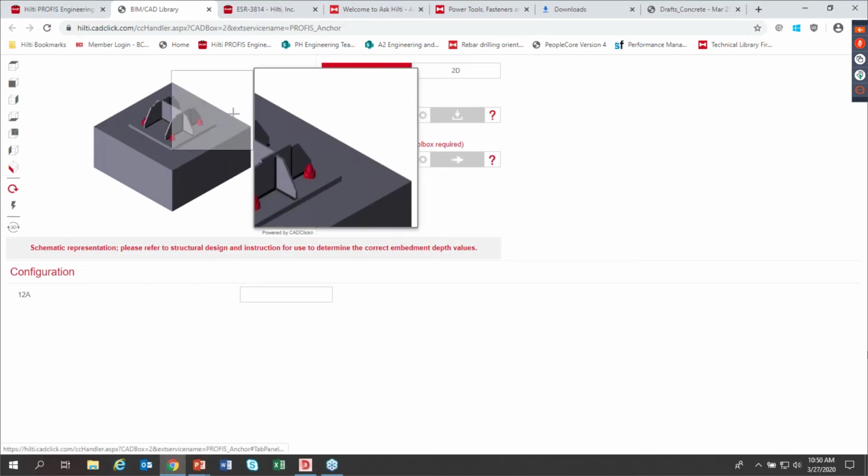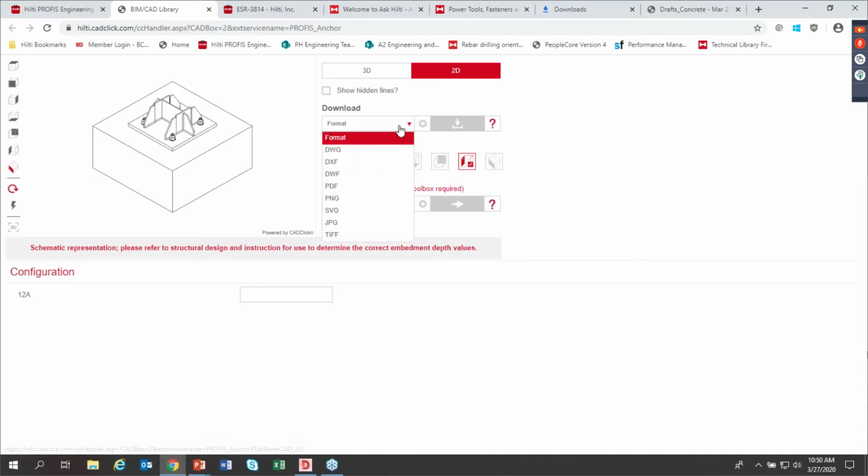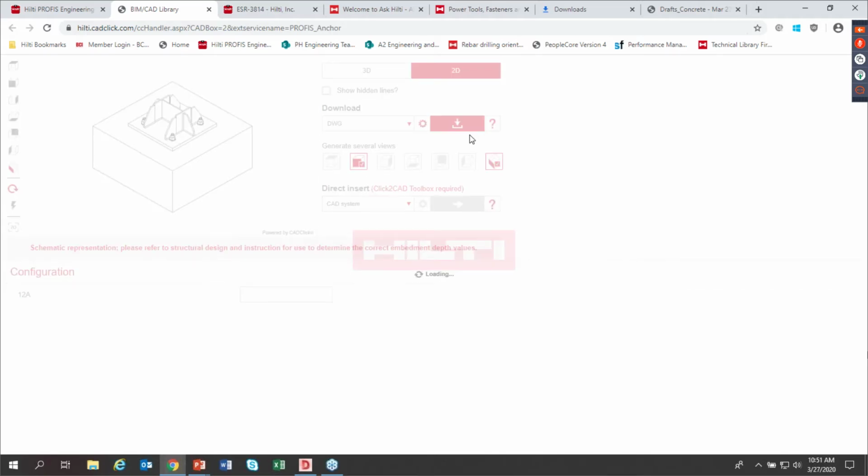So we can export it via 3D or via 2D. So other formats are shown here. If you are using AutoCAD, SketchUp, or any detailing software, we'll be downloading at least a front view and at least an isometric view. So it will be automatically depending on the format. So since I'll be using AutoCAD, I'll be using DWG software. So it will be automatically download to your software.